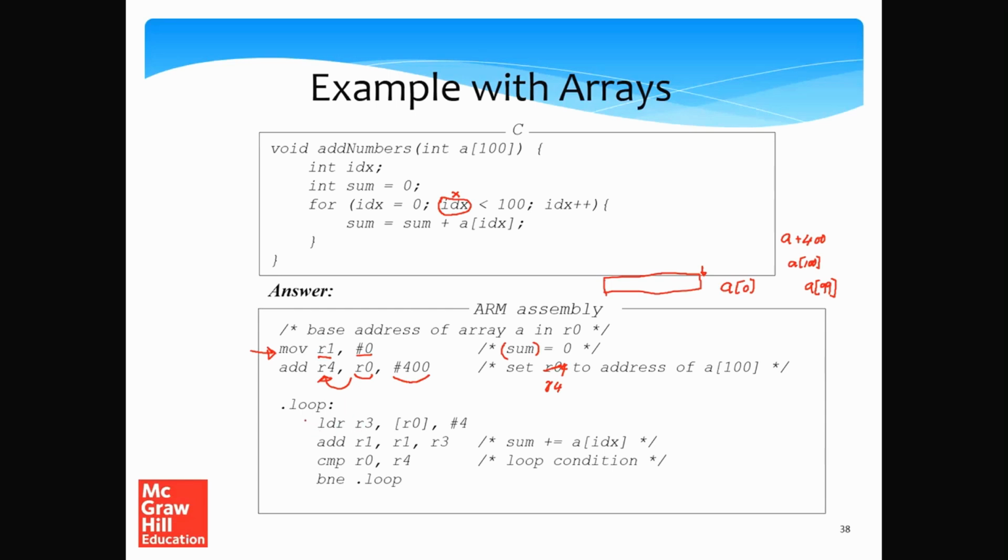So all the greatness of ARM pretty much lies in this instruction, which is the first instruction. R0 contains the base address, so we access R0, and the value is transferred to R3. Subsequently, we increment R0 by 4.